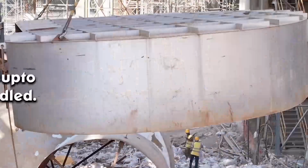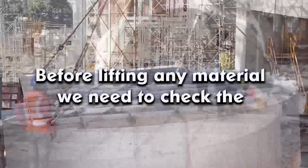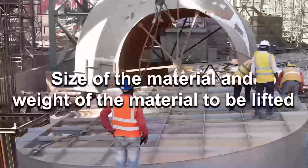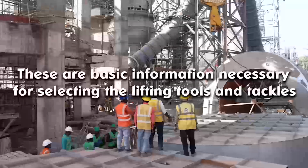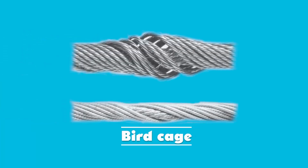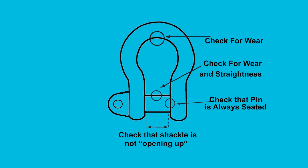Material handling. Structures and equipment up to 150 tons are lifted or handled. Before lifting any material, we need to check the size of the material and weight of the material to be lifted. Also, the center of gravity of the material to be considered. These are basic information necessary for selecting the lifting tools and tackles like slings and D-shackles. Slings to be checked for damages like broken wires, wear and tear, kink, birdcage, core protrusion, etc. D-shackles to be checked for wear and tear and distortion before taking into use.